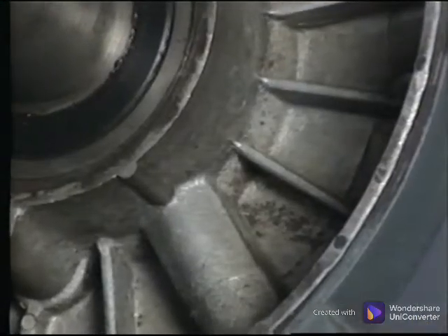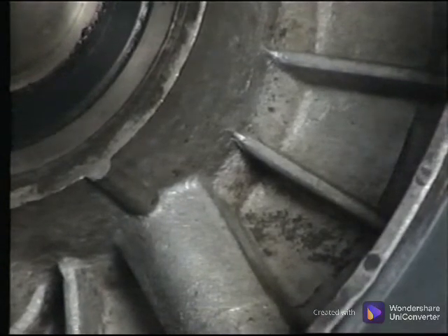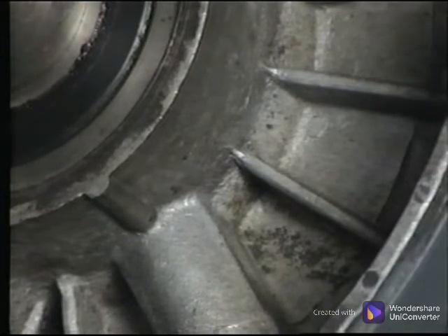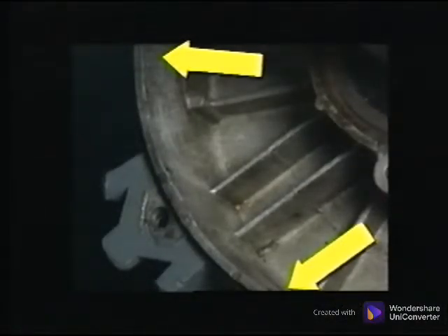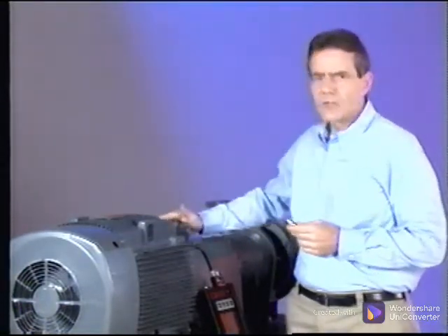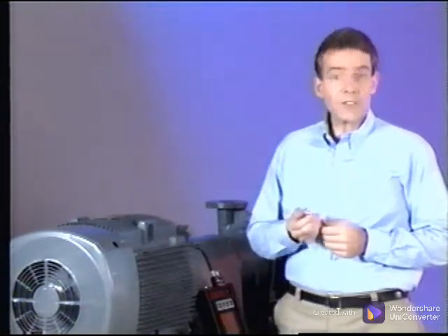The cover on the inboard end of this motor has reinforcing vanes molded into the casting. These will transmit energy from the bearing location to the sensor with little loss. However, the places without the reinforcing vanes are voids, and the energy is not transmitted as well to these locations. If you know the internal structure of the machine, collect the data where there will be a good solid path to the transducer. We need to use the characteristics of the sensor to maximize our results.